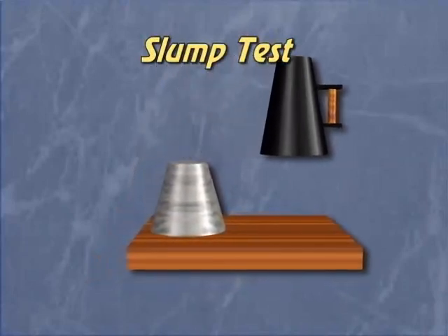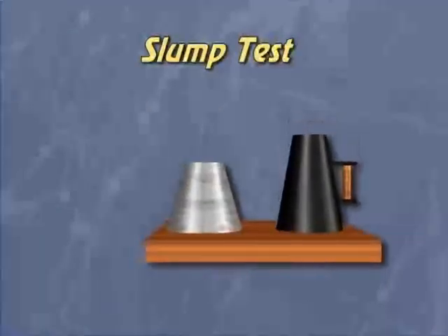Now, what happens is that concrete, since it's wet and hasn't set up yet, of course, will slump or sag down. And the amount of sag, or the amount of slump, is what is measured. The ideal amount is 2 to 4 inches. Now you can go ahead and write that into your book off to the side there. Depending on whether it's being used for a slab or a beam or whatever, a particular slump is given. Now, a 4-inch slump would indicate that the concrete is relatively liquid. A 2-inch slump would indicate that the concrete is relatively stiff.